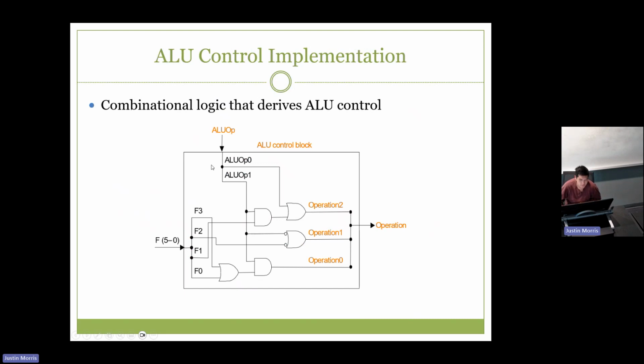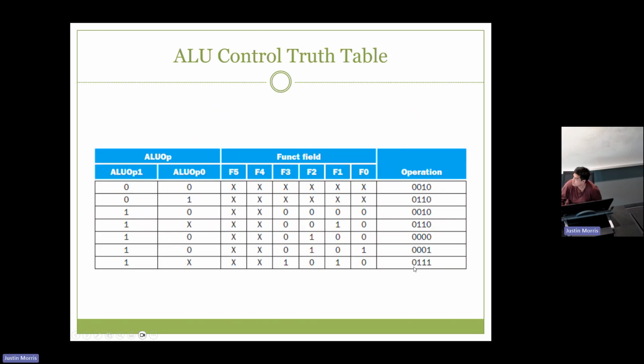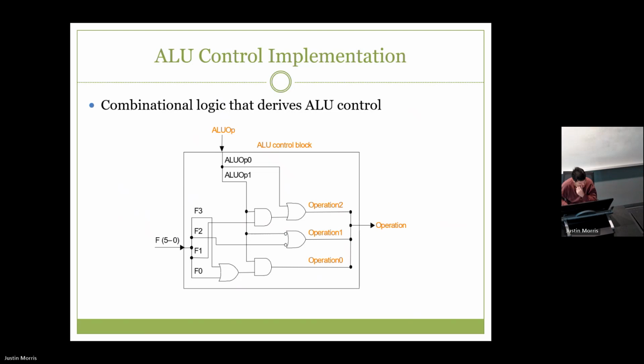And if you did some optimization and used that truth table, this is the circuit that we've come up with. Most of the time, we can figure out everything from just ALU op up. So we have ALU op and we have funct, and this simple digital logic circuit gives us our 3 outputs. It's different from 4 because here all of the most significant bits are 0. So this is our control block for the ALU control in the bottom right-hand corner.